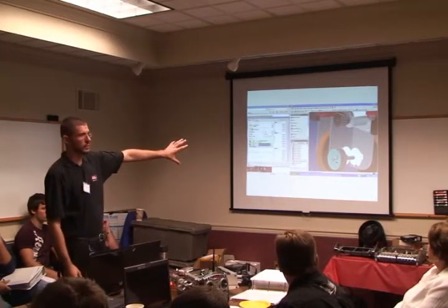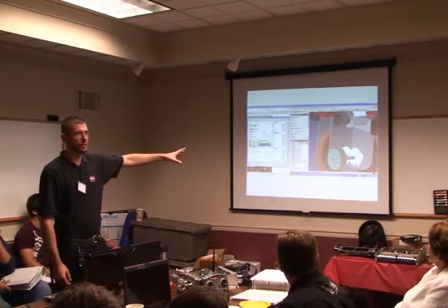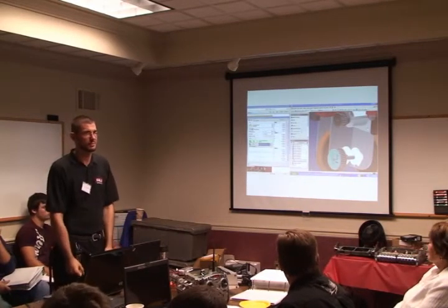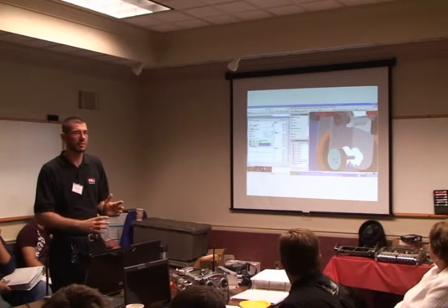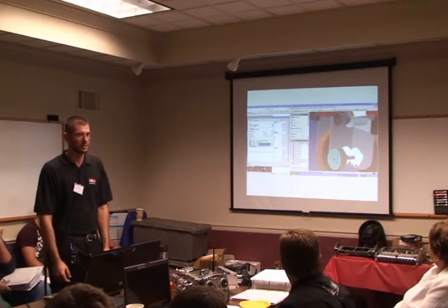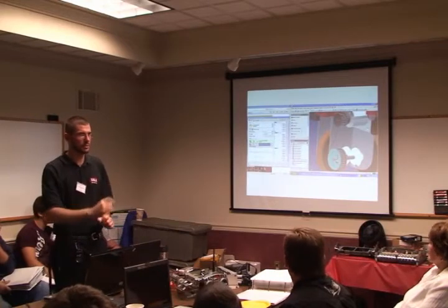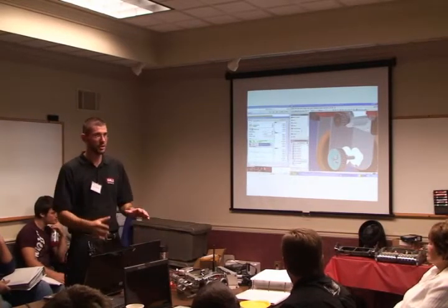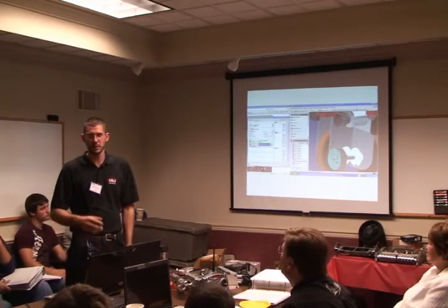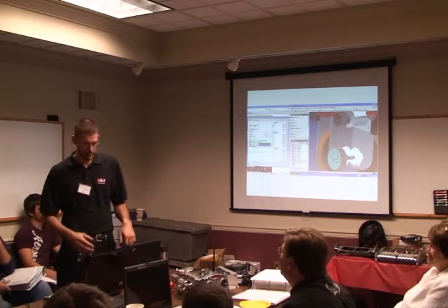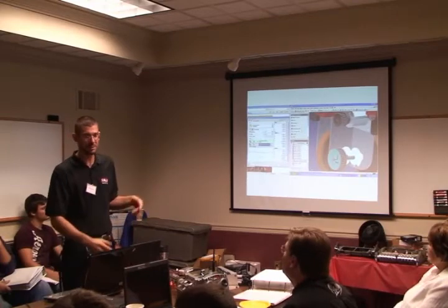What we did with this one is we made oval mounting holes on the frame so that we could pull the motor to tension the belt. That's how we got around not quite having the right size. So they're actually ovaled out. You can slide the motor up and down with tension on it. Might not work so well in a combat robot because it'll take a pretty good hit. The motor might slide, so you might not want to do that, but that's how we solved our problem.